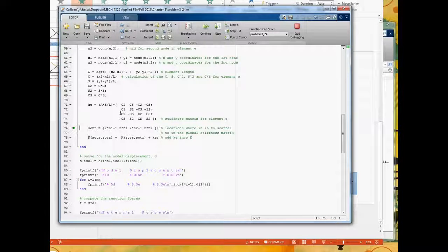All right, so I know for you this was no time, but actually that was a bit of a break, so I forget exactly where I was. I think I was describing the element loop. So there's 6 elements, so each time it goes to this loop, E will change from 1 to 2 to 3 to 4 to 5 and 6, and that'll allow me to compute K for the first element, second element, and so on. This here is basically just computing the element stiffness, and this bit here is putting it into the correct location in K. So let's talk about that a little bit.